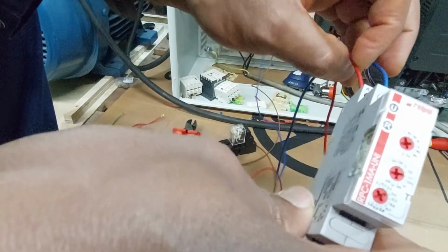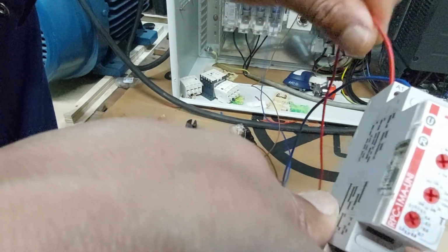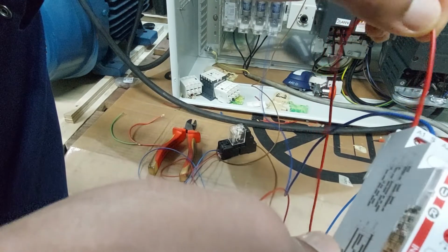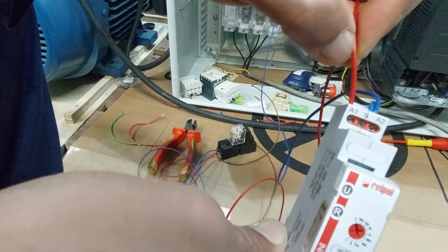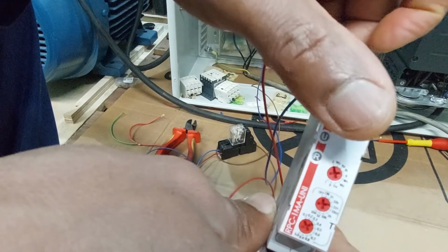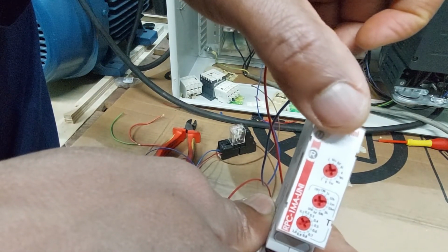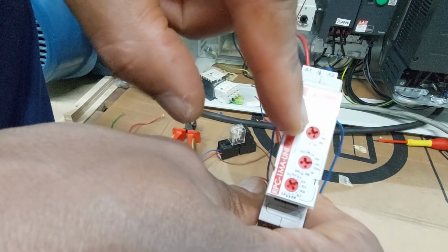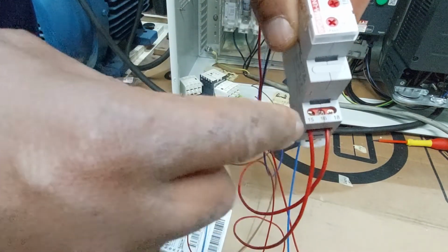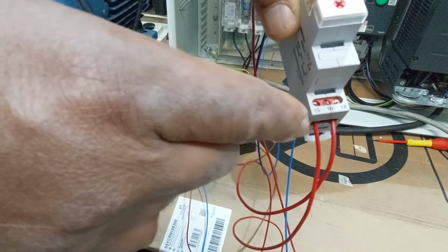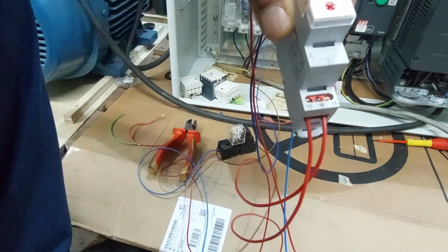You know that how a timer works is that when it receives voltage through the A1, then it will activate the timing. And then when the time that you set has been reached, it will move the switch. This is the switch that it moves. So this is how to use it in a project.